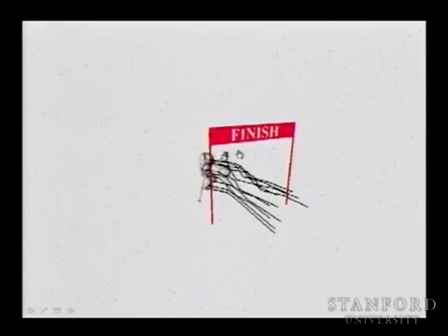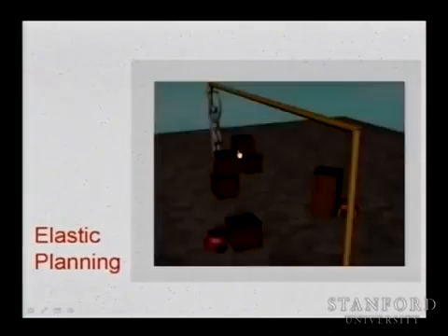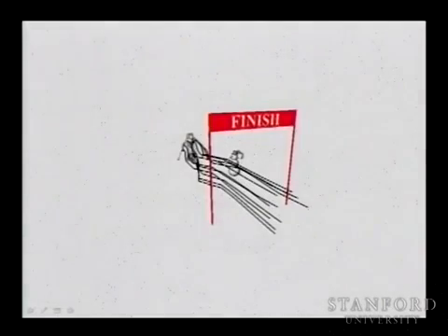The reason is, I'm not sure if you're familiar with the problem. Oh, sorry, let me just stop it here. The problem of motion planning in robotics is exponential in the number of degrees of freedom. So usually if you want to replan a motion when one obstacle has moved, it would take hours to do, for a large number of degrees of freedom. And here we are able to do this quite quickly because we are using the structure and we are using this concept of repulsive forces that modifies future configurations and integrates.